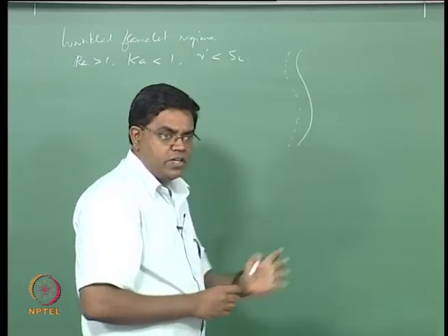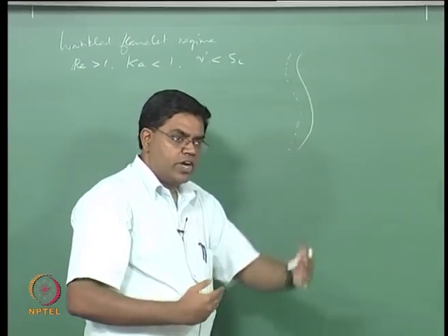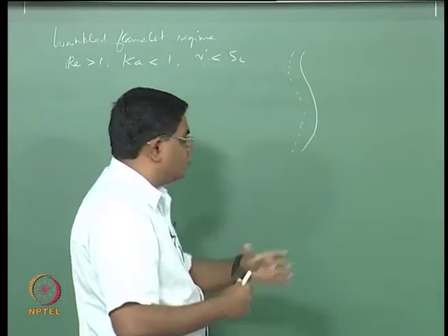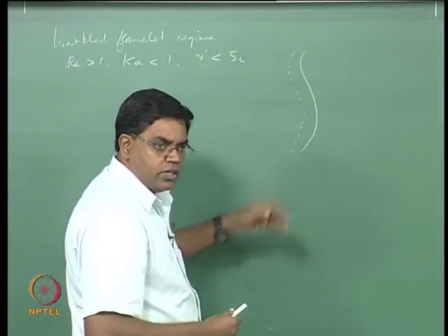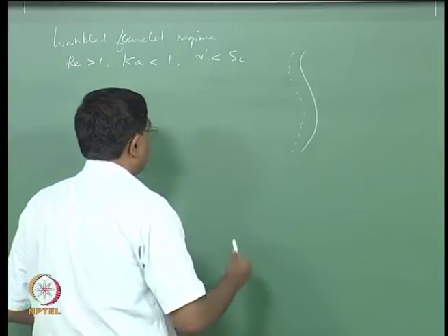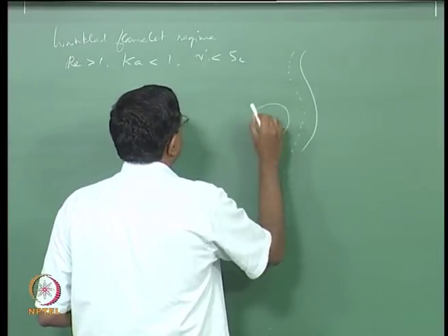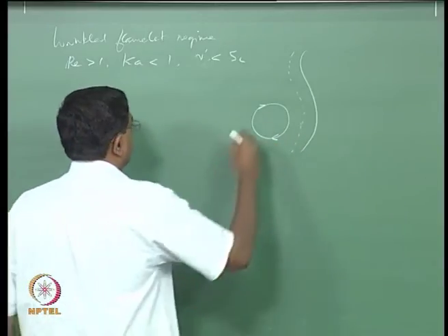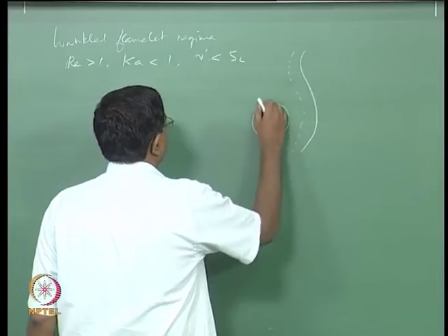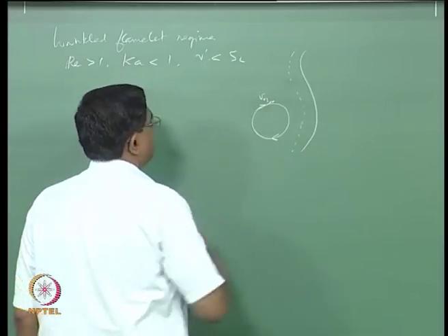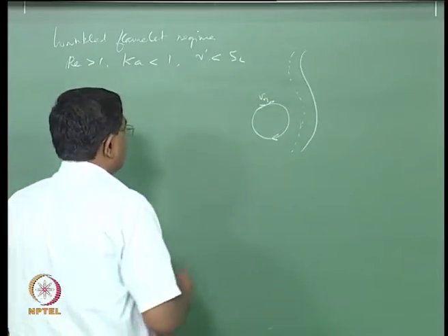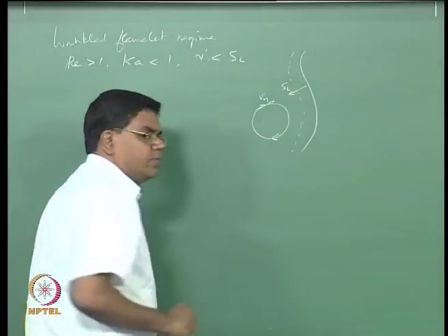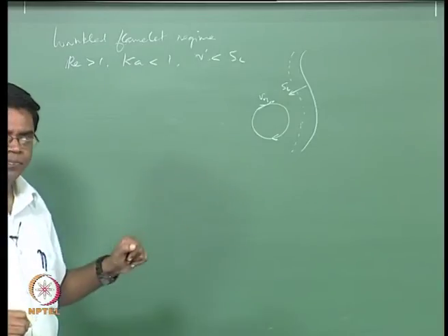Effectively, in a one-dimensional flame you would have the reaction zone, and upstream of it you will have the preheat zone. So the upstream edge of the preheat zone is what is marked by this broken line, but we are now showing it as curved because it is now interacting with an eddy that is going around like this. Its tangential velocity is Vn, depending upon the eddy size, and this flame is now propagating locally normal to itself with a flame speed SL.